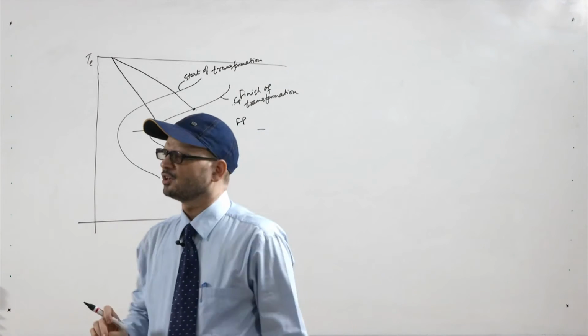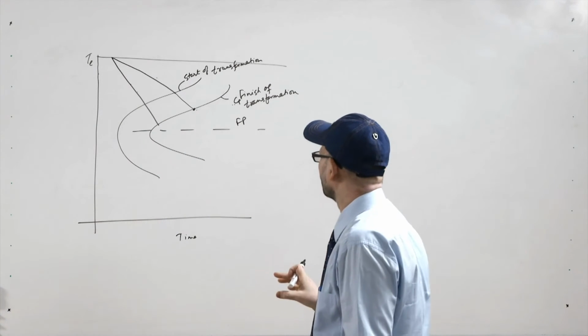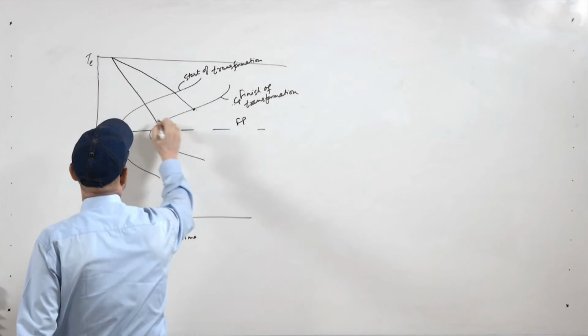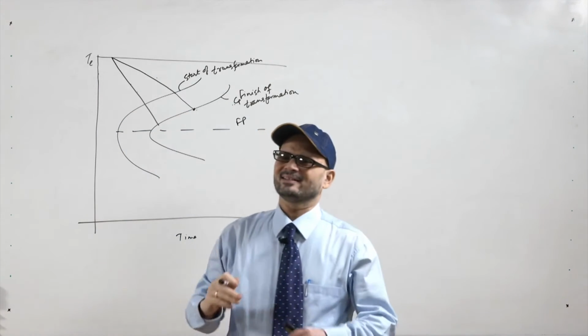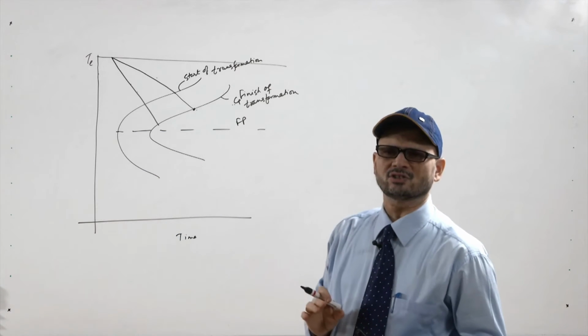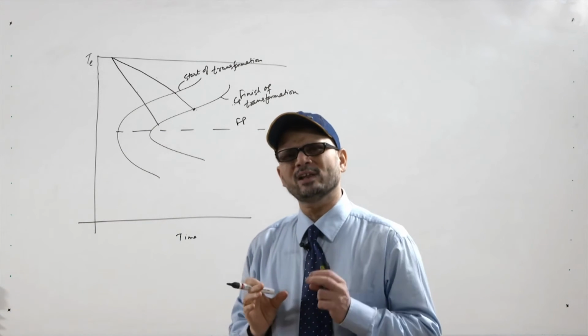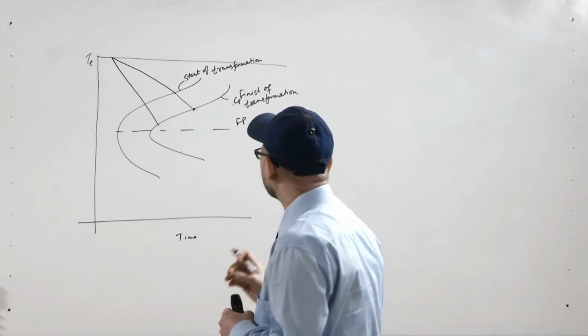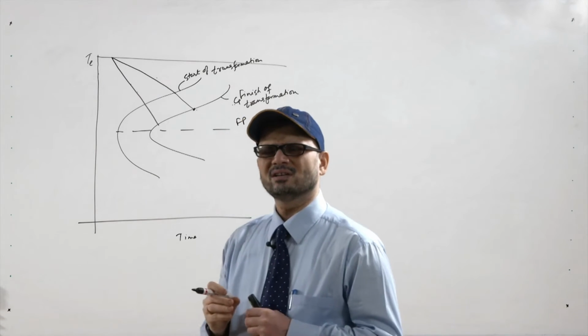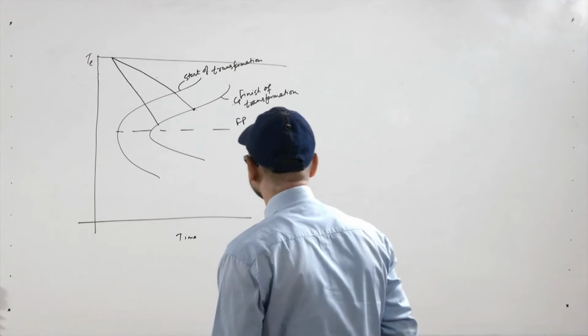If it crosses through the nose of the C curve, there is formation of pearlitic structure, and depending upon the cooling rate you have either coarse pearlitic structure or fine pearlitic structure.